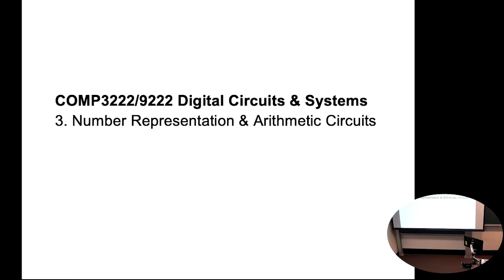In the first two lectures, we talked about Boolean functions, or what's known also as combinational or combinatorial functions, and simplifying those, and techniques that we can use to simplify them. And we've looked at multiple ways that they could be implemented, both in various sized lookup tables, which is sort of the raw logic resource in FPGAs, or as NAND and NOR only gate circuits if you were targeting some sort of ASIC process or custom VLSI process.